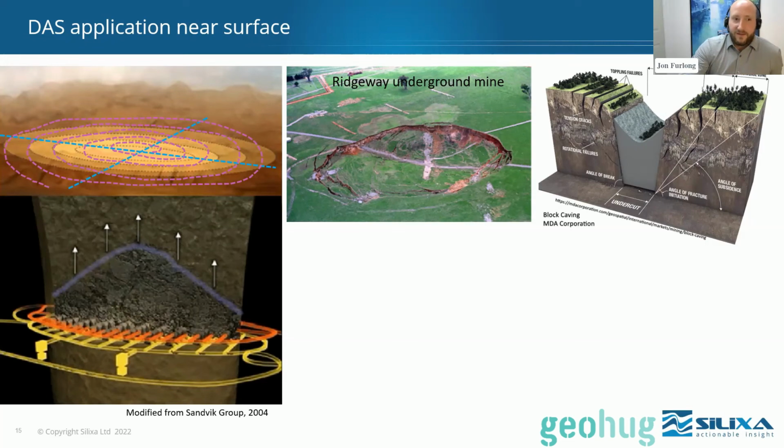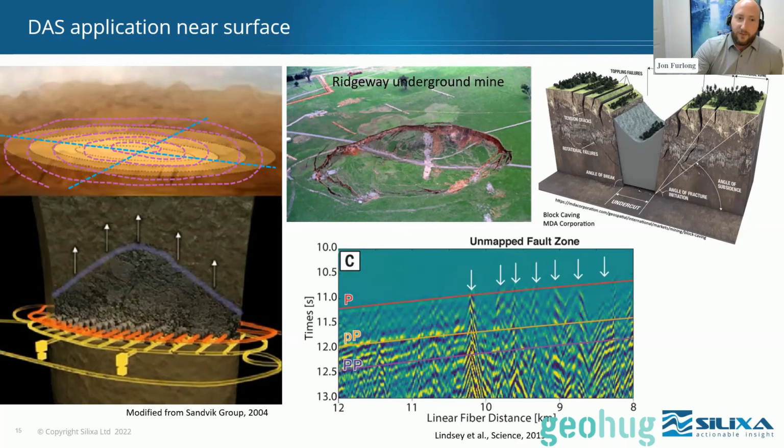And we've actually had success in an example here from offshore California, where they had an ocean bottom seismometer 15 kilometers off the coast that was down for maintenance, and it was connected to the surface with a fiber optic cable. So when it was down for maintenance, we interrogated that fiber with the DAS unit, and we were able to map all these faulted zones that were otherwise unknown to be there, because we have that higher amount of spatial resolution. And the source for that was just microseismic events or seismic events coming in off the coast and rolling through.